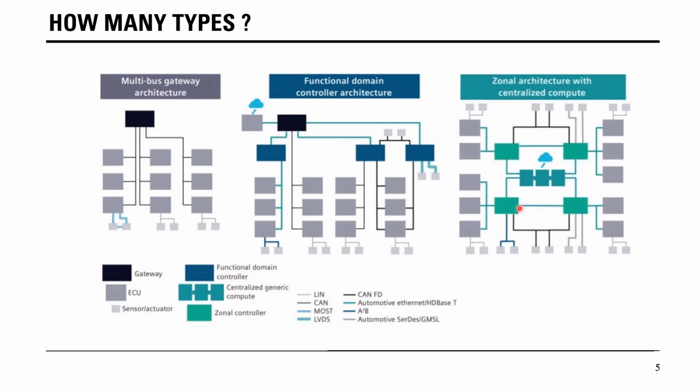As you see in the green box, the vehicle has been divided into several zones and zone controllers have been established there for more computation of the data which is coming from the peripheral ECUs or sensors directly to the zonal controllers. And then we have a centralized computing system connected to these zone controllers as well as external ECUs indirectly, and then sharing data to the external world for different kinds of software updates and various other features of the vehicle, like entertainment systems and so on.